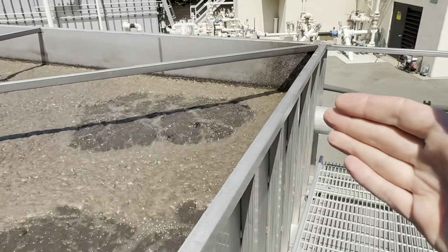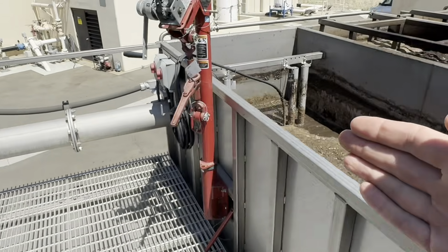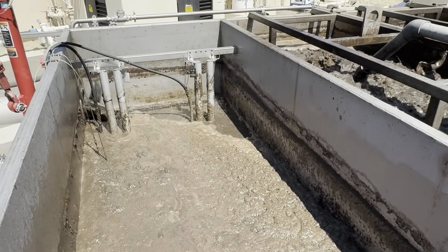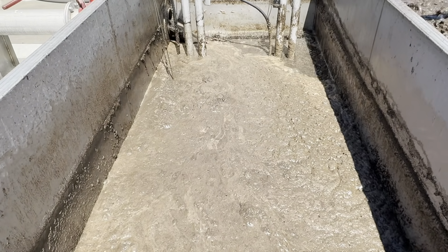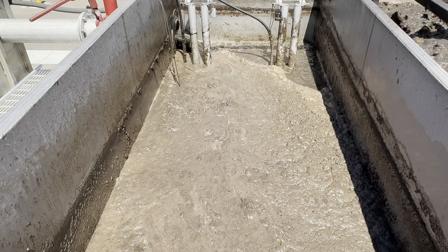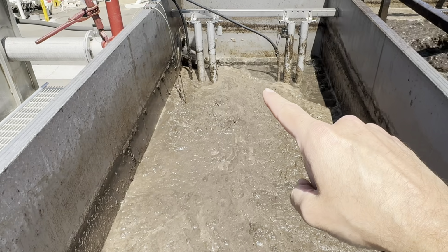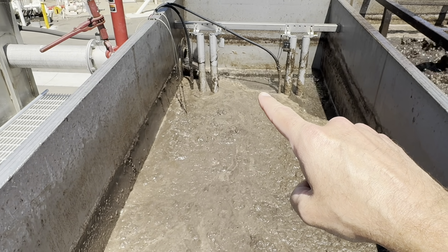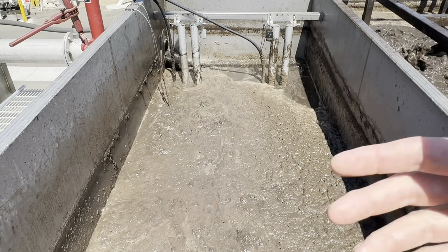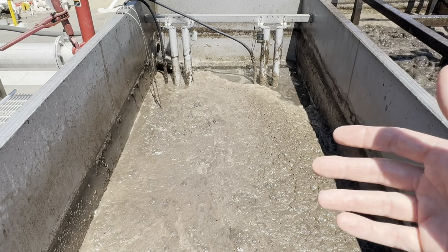And so from aeration, what happens is we transfer over, and normally this would be going over to a clarifier, but I've got membranes, so I'm going to explain what you're seeing here. This would act kind of like a stilling well would. You see a little bit of foam carryover. It's not a big deal. You can actually see it's not much foam given the level of the mixed liquor coming in. It's just kind of annoying. If it was to become a problem, I would have to deal with it, but it just hasn't.